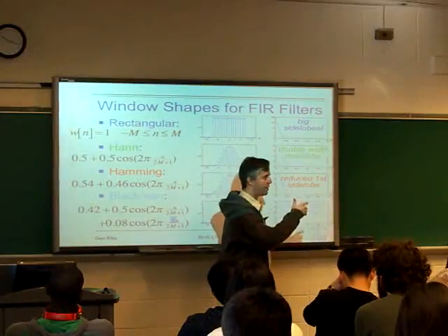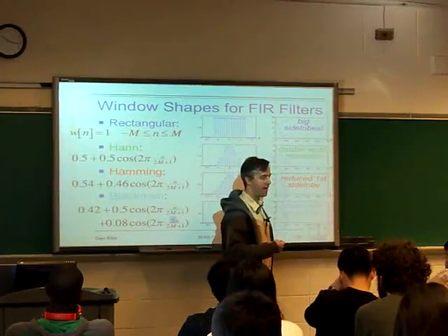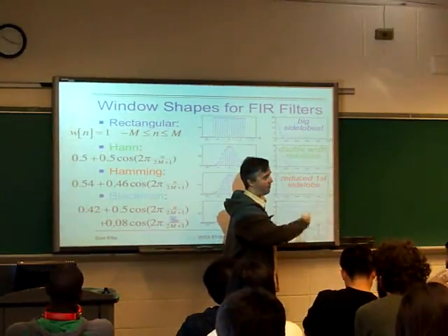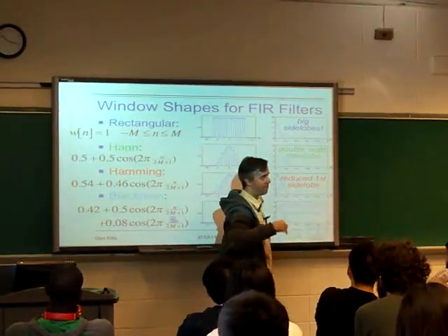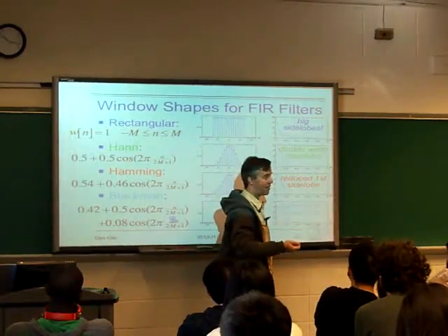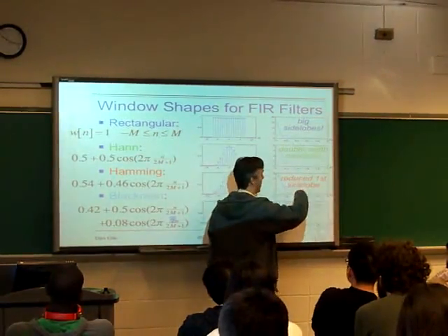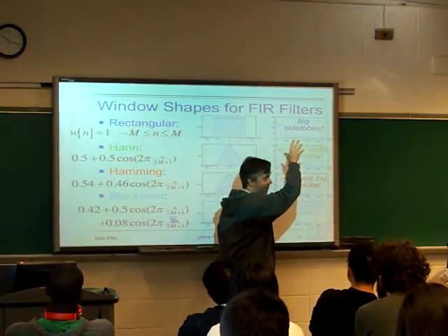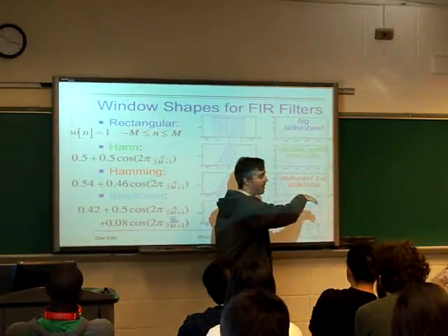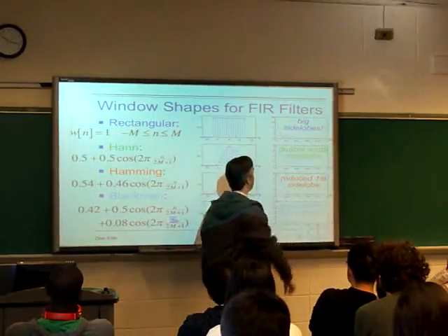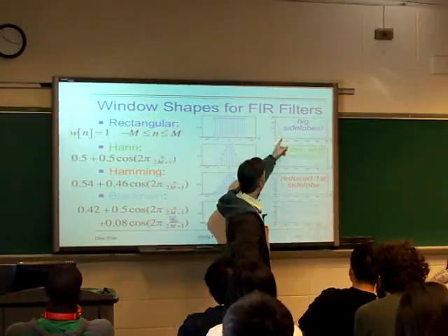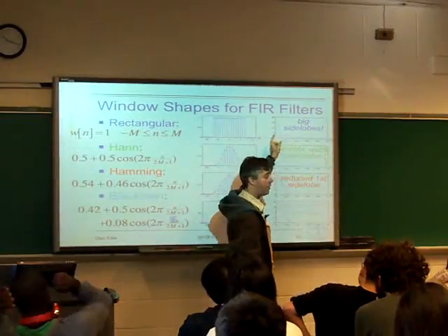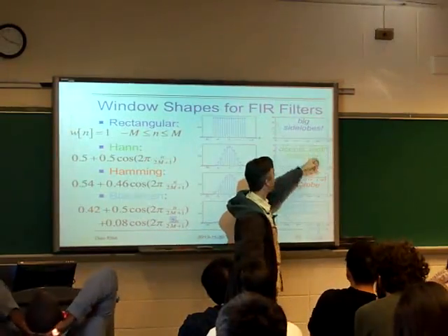It's actually sine nx on sine x, the periodic sinc function, but it means that it goes through 0 every time nx equals a multiple of pi, except at 0 where it's sine of n times 0 divided by sine of 0, which gives us the 1. But it's got the main lobe, and then it's got these zeros, but in between it sort of falls off as roughly 1 over n. Right? They die away quite slowly.